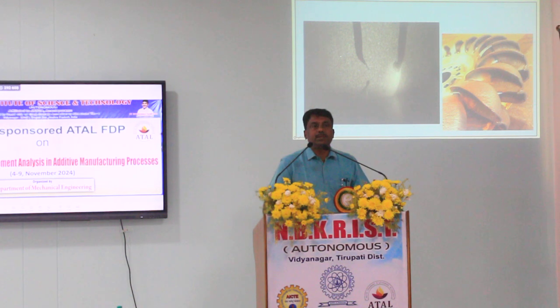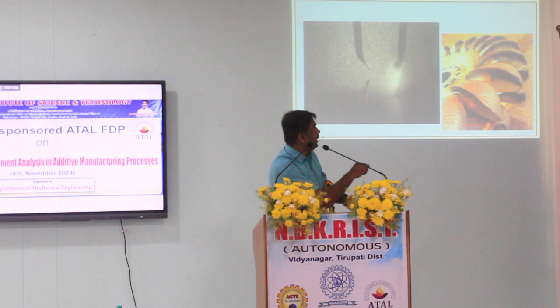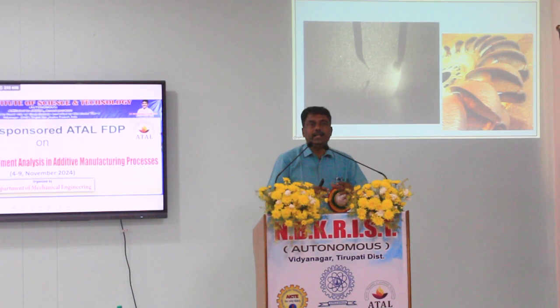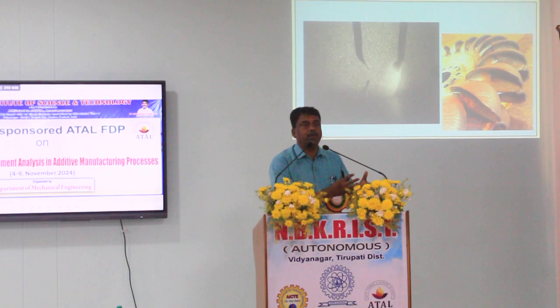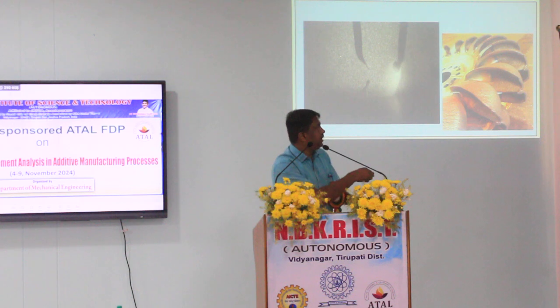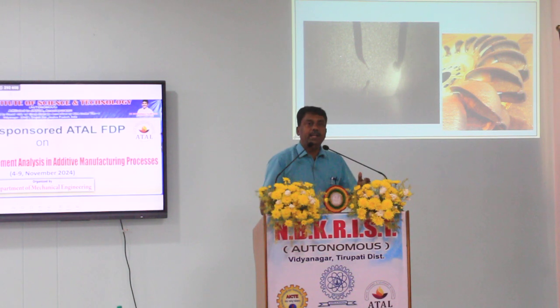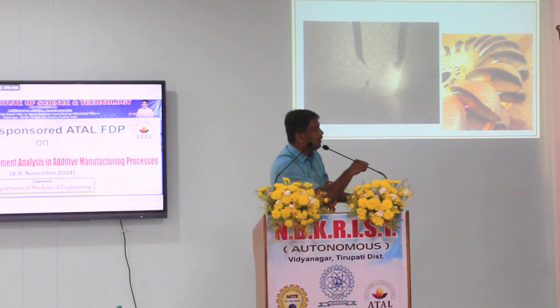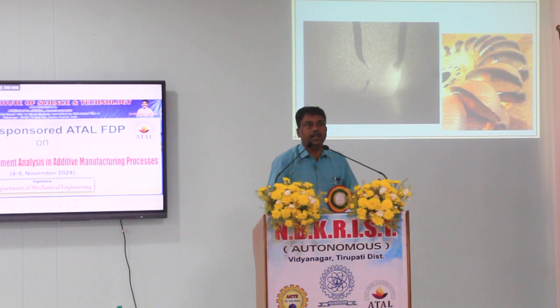So we need to get both high fatigue resistance and corrosion resistance. Right? So conventionally, if you want to make this impeller, it is impossible to produce with multi-material. So we have to make a shaft, machine it out, and then weld each arm individually. Then the weld becomes the weak link over here, so you're prone to failure.